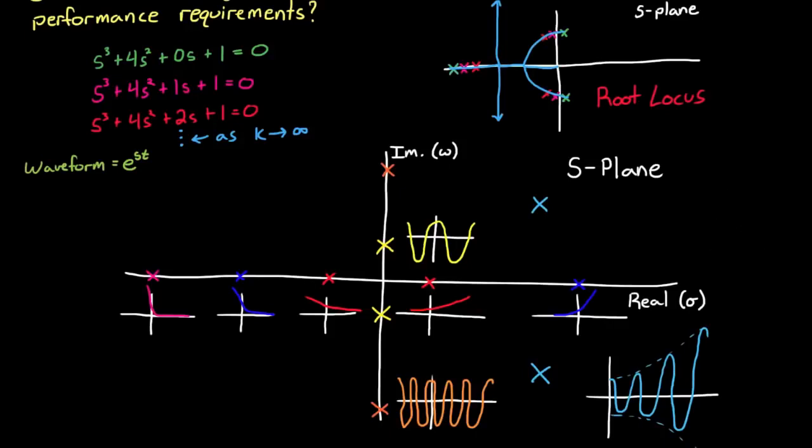Even though both poles and zeros of a system are needed to characterize the response to a forced input, only the poles of the system are needed to dictate an unforced response to a set of initial conditions. And this ties directly to the stability of a system. And that's why when we're talking about stability of a system, we're really only looking at the poles in the